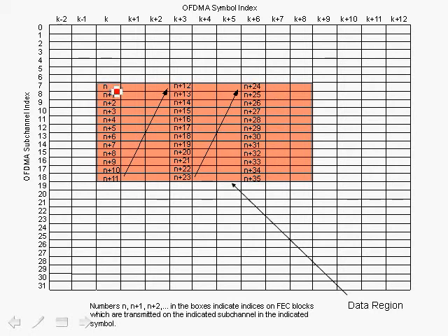Now, if we look at the carriers within this data region, then they're all permuted and none of them are necessarily adjacent to each other, and we meet our requirements in terms of robust communication over fading multipath channels in this case, and the permutations are based on the description we gave.